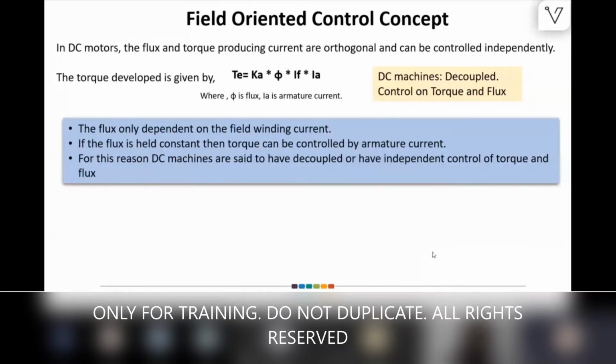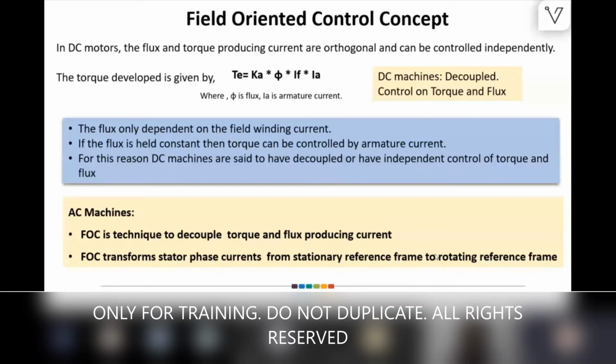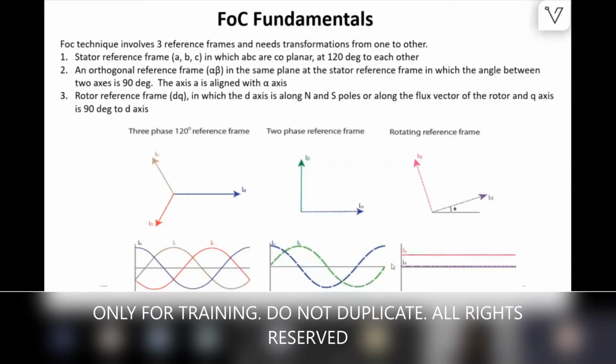So this is nothing but a mathematical implementation. It takes the three-phase current and makes them mathematically behave like a DC. You can see ID and IQ are like a constant current, like a DC current. Through some mathematical transformations, Park and Clarke help us.